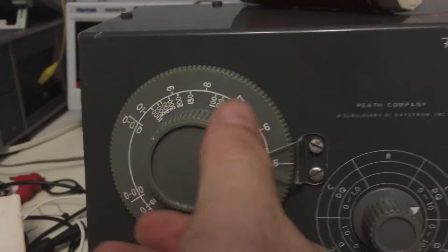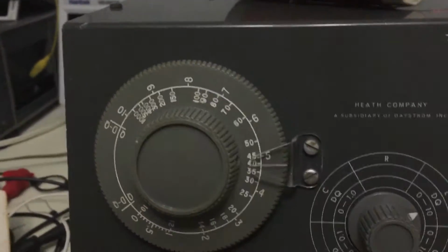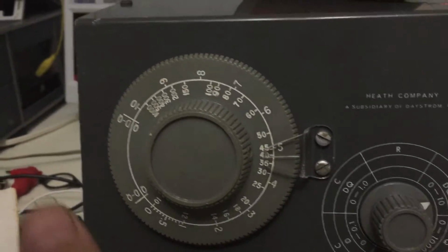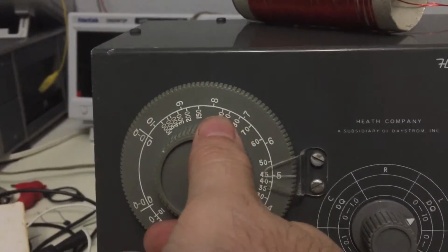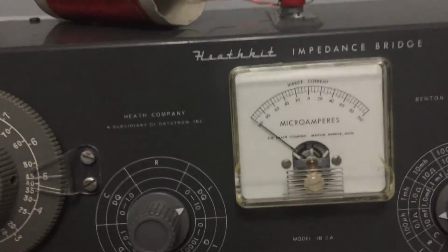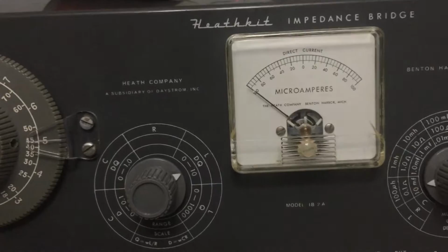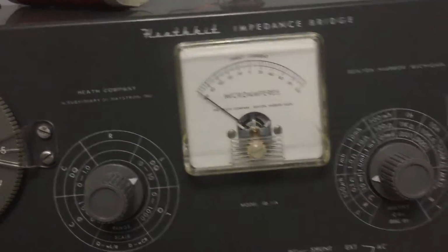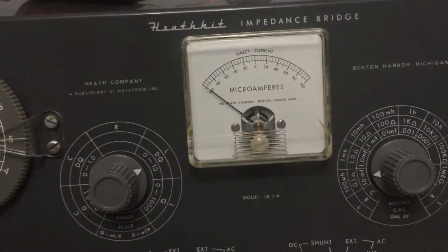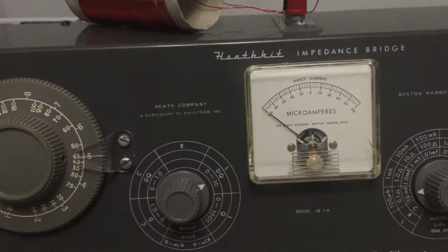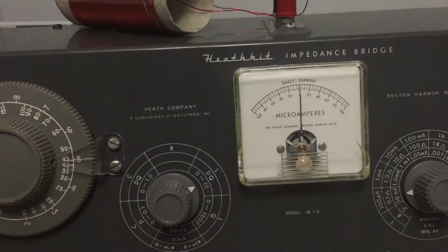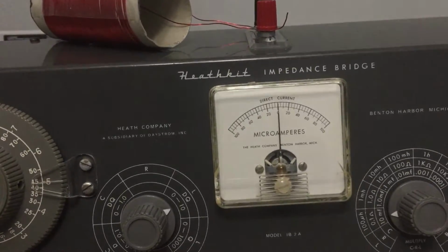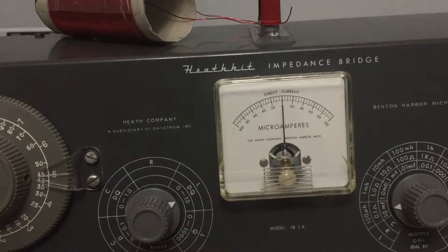So the detent in mine is right there, but I'm not using it because the calibrated position of 5 is right here. So kind of stupid. But anyway, once you do that, very much like the capacitor, we make sure our gen level is all the way down. We set our AC level right here to 0, and then once we're at 0, we turn our direct current, or we turn our generator level up till we balance this.